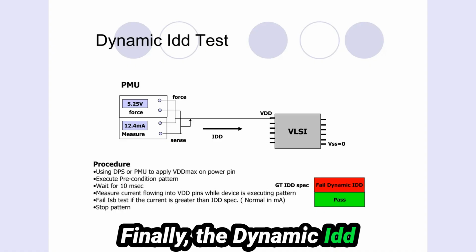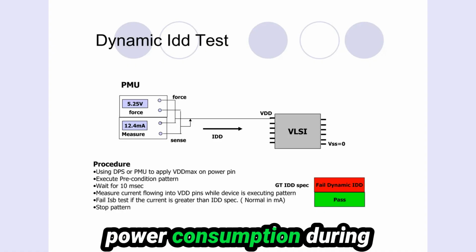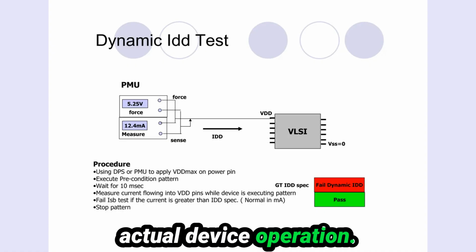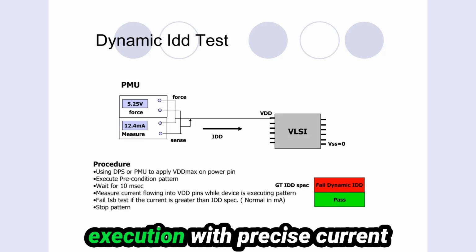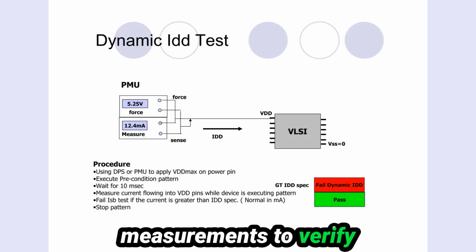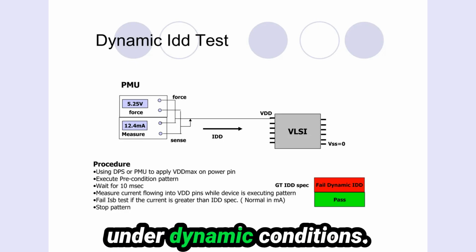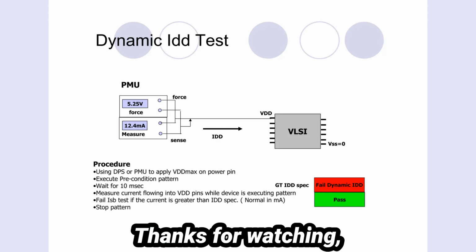Finally, the dynamic IDD test, which measures power consumption during actual device operation. This test combines pattern execution with precise current measurements to verify proper power consumption under dynamic conditions.